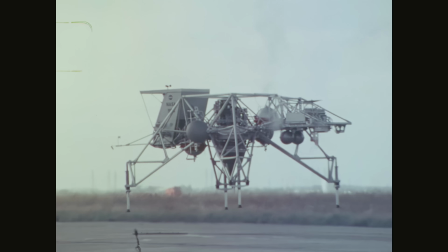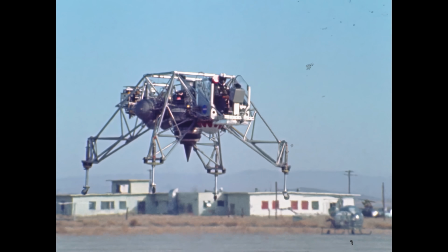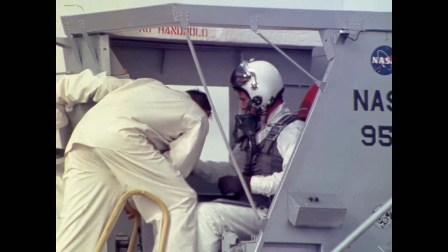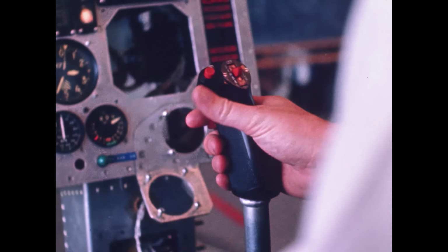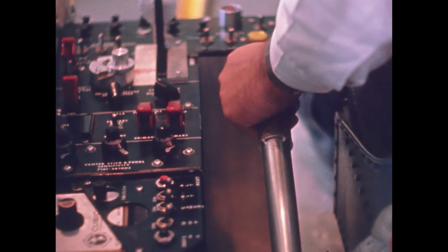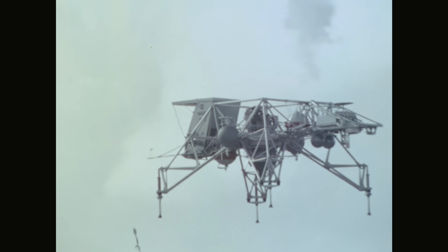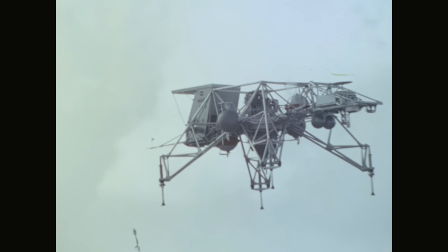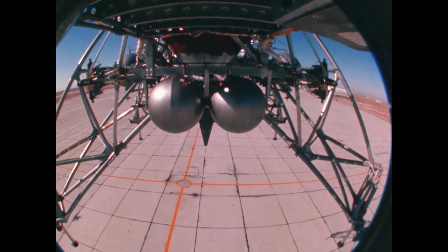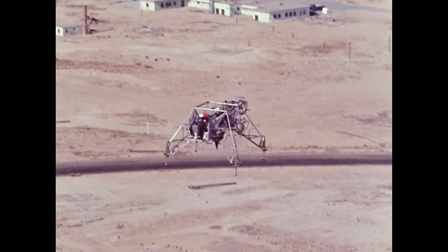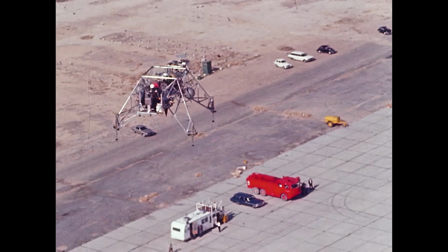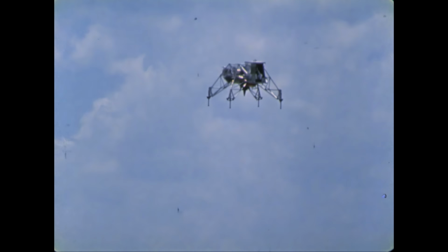And so the Lunar Landing Training Vehicle, or LLTV, was born. It featured a partially enclosed cockpit with LEM-like visibility, a 3-axis control-mounted side stick, a lift rocket throttle replacing the collective, LEM displays, and a rate command attitude hold system that closely approximated the expected lunar module performance. The LLTV proved to be an excellent simulator and was highly regarded by the Apollo lunar module crews as necessary to lunar landing preparation.